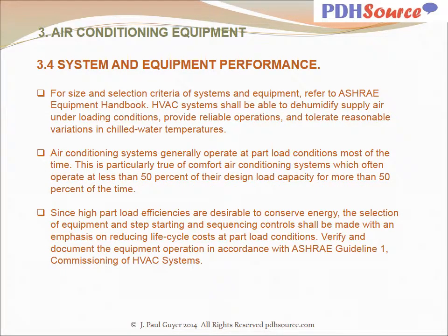For size and selection criteria of systems and equipment, refer to the ASHRAE Equipment Handbook. HVAC systems shall be able to dehumidify supply air under loading conditions, provide reliable operations, and tolerate reasonable variations in chilled water temperatures. Air conditioning systems generally operate at part load conditions most of the time. This is particularly true of comfort air conditioning systems, which often operate at less than 50% of their design load capacity for more than 50% of the time.